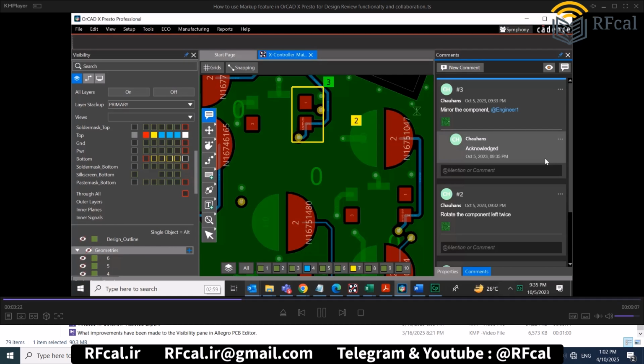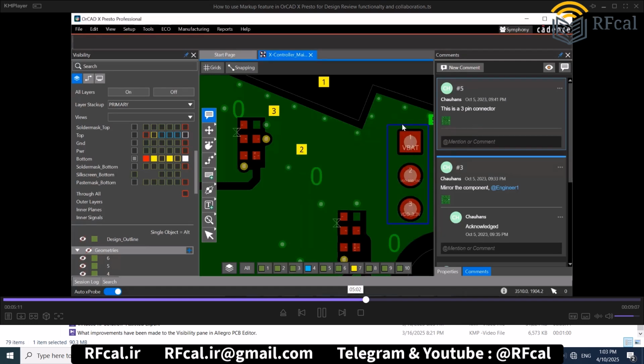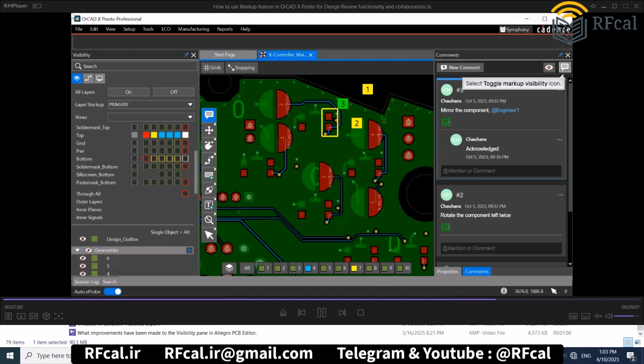You can also edit comments and markups in Allegro or Cadence. Select the markup from the design canvas, right-click and choose Comments panel. All the markups become invisible in the design canvas, however the comments remain visible in the Comments panel.